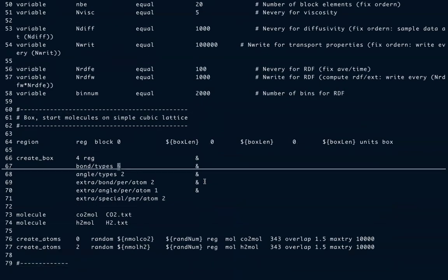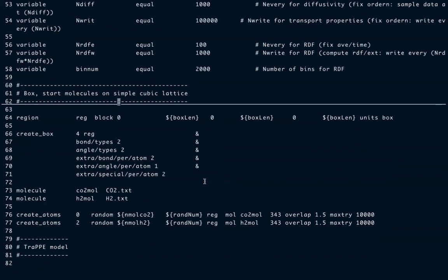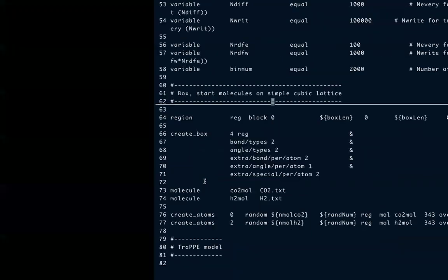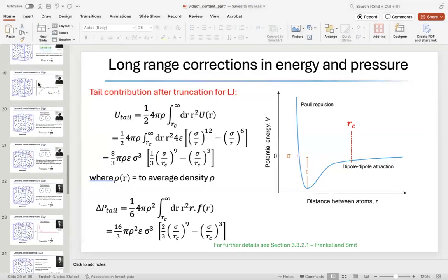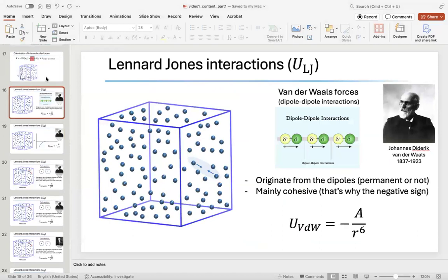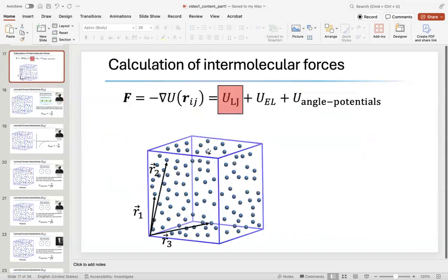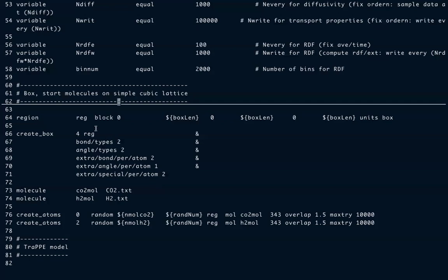Okay, so the next important step is to initialize. Like I said, the beginning of any molecular simulation requires you to first initialize the particles or the molecules inside a box. So you can always picture this particular image in your mind, and this is what you need to generate. Now, I've written a command here which says to LAMMPS that you allocate a region called REG.